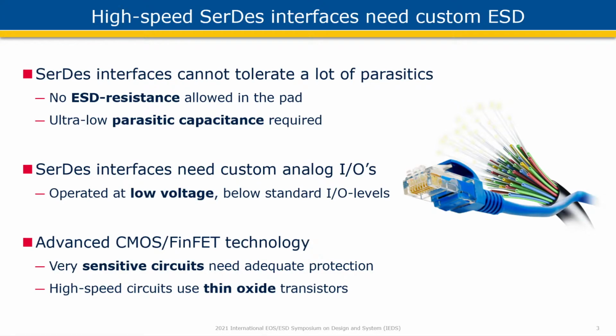There are three main reasons why high-speed SerDes interfaces need custom ESD protection. First, SerDes interfaces cannot tolerate a lot of parasitics. There is no ESD resistance allowed in the pad, and ultra-low parasitic capacitance is required.